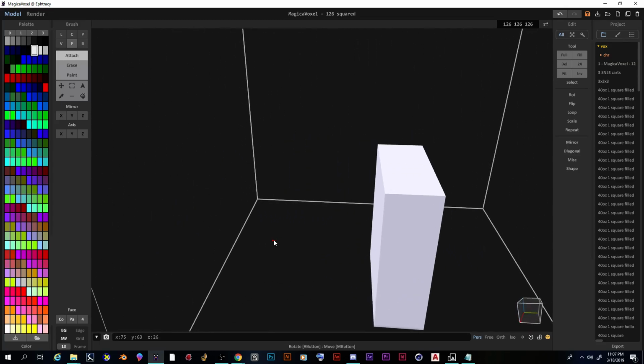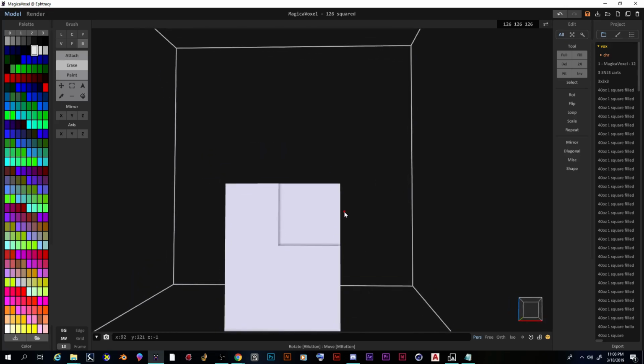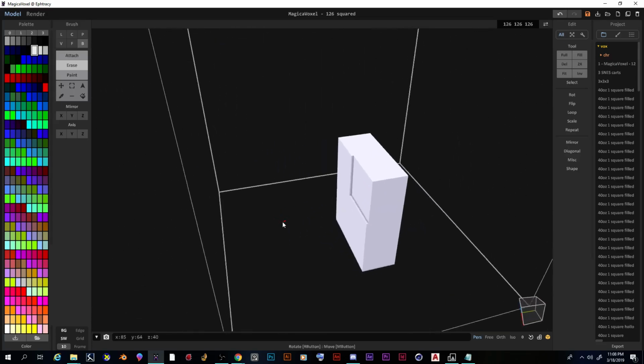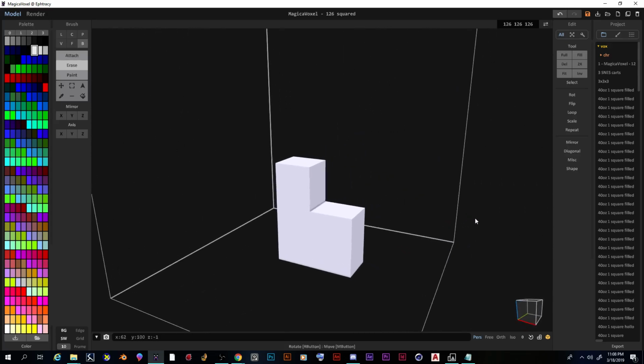Okay, next, this is like a chunk of marble. I want to carve some things out of here, like the body of this. So I'm going to click on my box brush, and then instead of being on attach, I'm going to go to erase. And I'm going to click and figure out how far I want this to go in. See, I'm zooming, I'm going at a different angle. I'm just clicking and dragging, taking this away. I could do it like that.